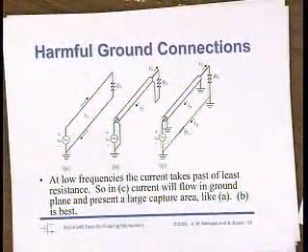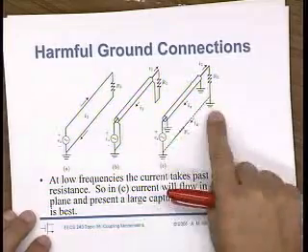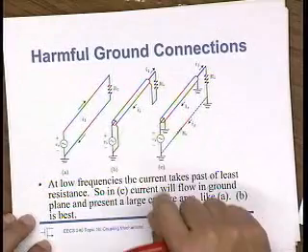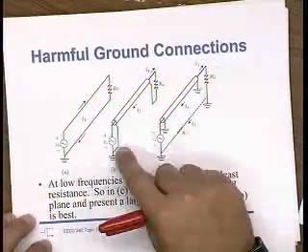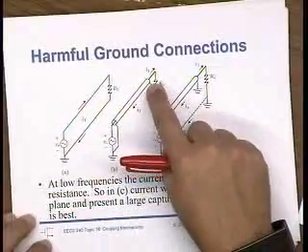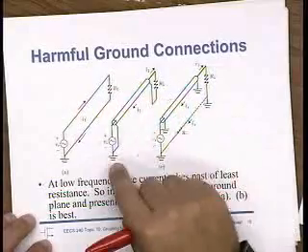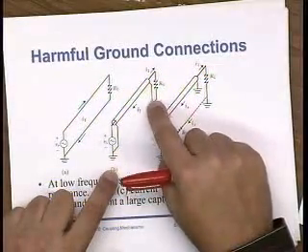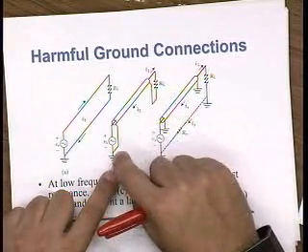So this is in fact why it's actually smart sometimes to avoid too many ground connections. Because what you can see here is, let's look at three cases. Of course, this is the worst case, right? There's no shielding at all. So here, I do the smart thing and I put in a shield, and then instead of grounding both ends, I just ground one end. On the other end, I just connect the negative terminal of my load directly to the shield. And so I ground the load through the shield.